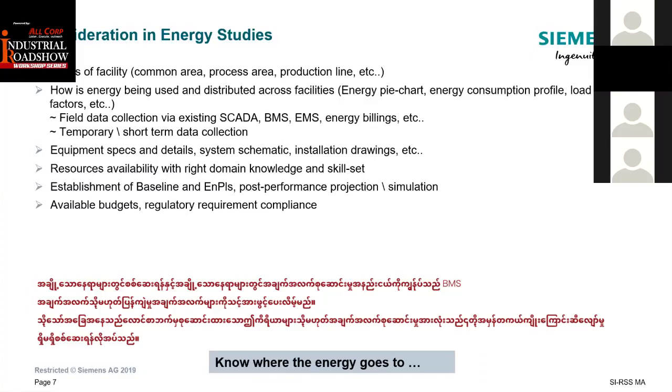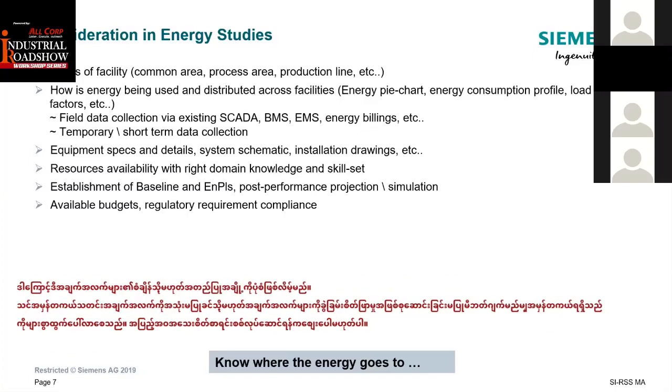For field data collection for a level 2 audit, in some locations I am open to also using BMS data or SCADA data. But the condition is that we need to verify whether all this instrumentation data collected from the field side is logical or realistic. So this is some form of validation of data before you actually use the collected data for analysis.